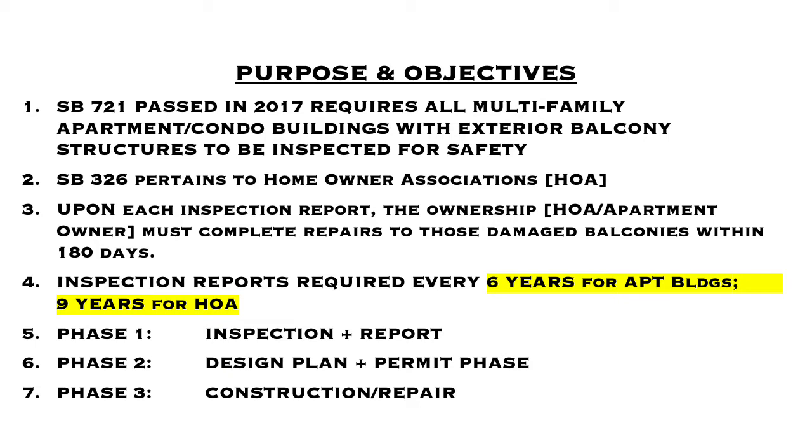But the important thing to know is that on item 3 here, there is a mandatory requirement to complete repairs within 180 days. And I'm actually required under both laws to report anything that I find that's damaged to the local building authority. There are 3 phases, phase 1, 2, and 3.